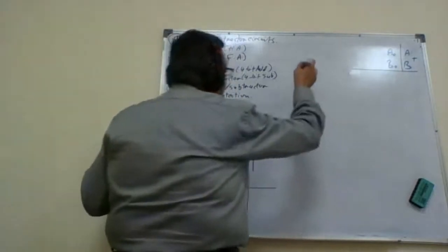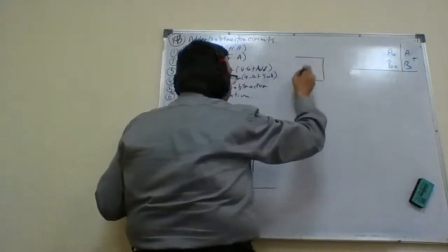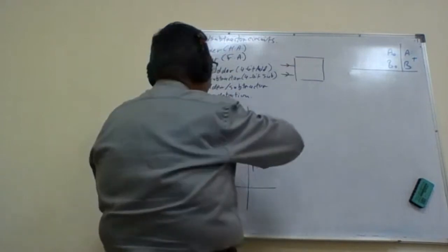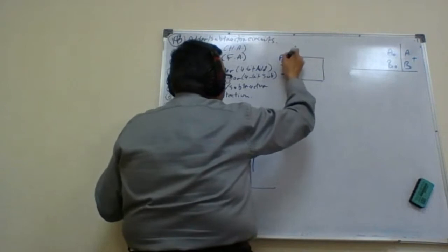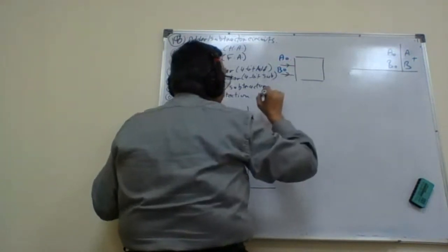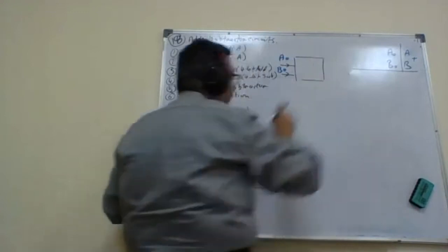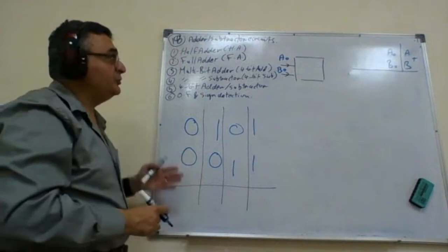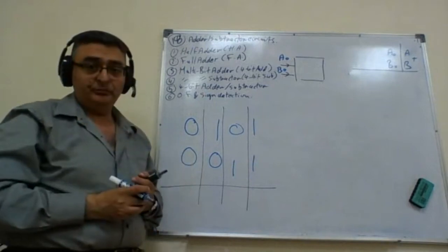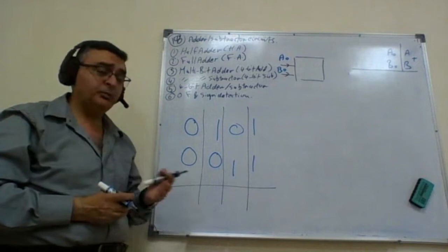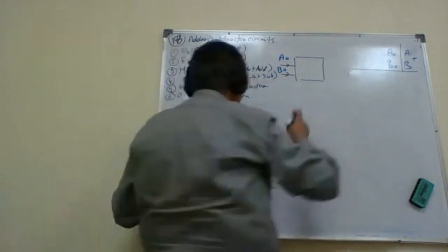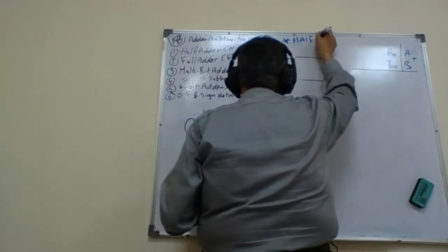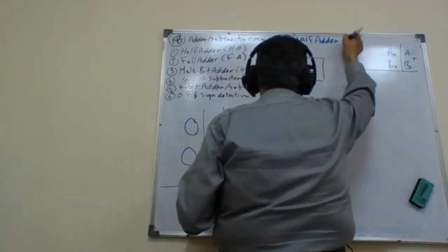So if I'm to draw a block diagram for my circuit, right now we at least define that the circuit has input A0, input B0, and the circuit should perform an addition between those 2 bits. How many outputs do you expect for this circuit? This circuit is adding 1 bit to 1 bit. By the way, we call this circuit the half adder circuit, HA.